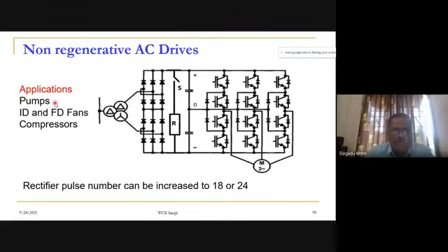In these applications, once the fan or pump is switched on, it may be on for a week. Similarly in the case of process industries, we don't require regenerative braking when we don't want to stop the machine frequently. Whereas for pumps and fans, when you stop them, because of the fluid or air, they automatically get a braking effect.